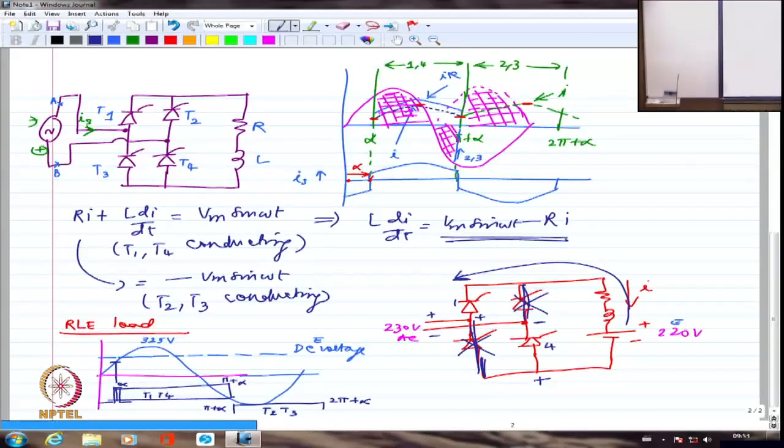But a continuous long duration pulse I normally do not give for an SCR because I use a pulse transformer. Please correlate the two. I connected a pulse transformer to isolate the gate from power. All these things are in the gate. All these things are in power.